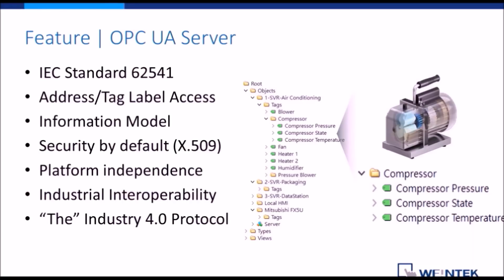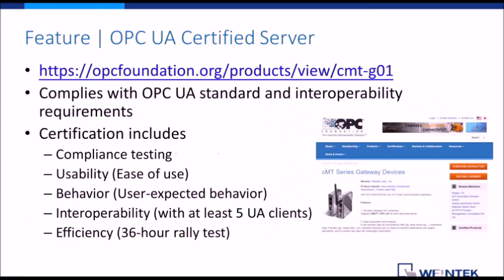Okay, and some other key points is that OPC UA is secure by default. It uses an X509 certificate exchange for security and encryption, and this is basically the industry standard right now. And it's platform independent, so there are apps that work on our machines, on Windows, on Android, etc. And the details. Okay, so well, if you really need to know, this is the thing to know.